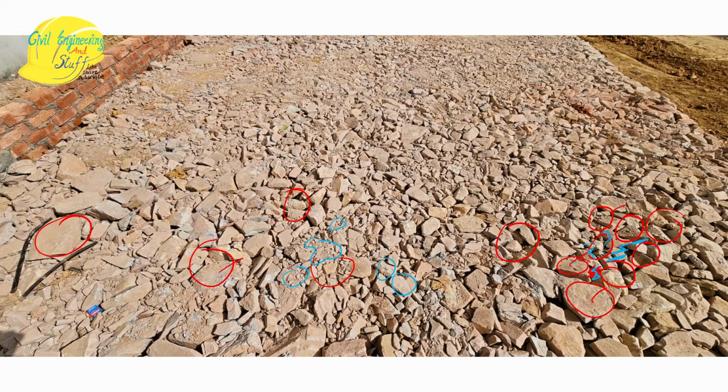So, what does it include? The first stage is laying of coarse aggregate, and then compacting them, right? Second stage is laying of fine aggregates or the screens in between, and the idea is to fill up those voids with this fine material. And then the third stage comes where the water is sprinkled over the layer. So as the name suggests, water-bound macadam means the material is bound with the help of water. Got it? So these are three stages in which the WBM layer is laid.